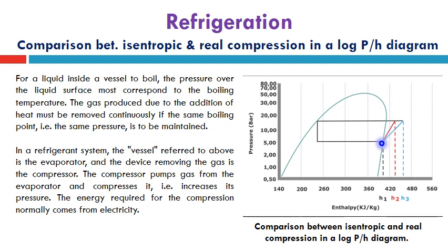However, if the problem has isentropic efficiency less than 100% and the compression process is not an isentropic process, and just adiabatic or non-adiabatic and non-isentropic, then the compression line will go to the right of the constant S line, with the difference which makes the projected area of the compression from point 1 to point 2 larger than the projected area of isentropic compression.